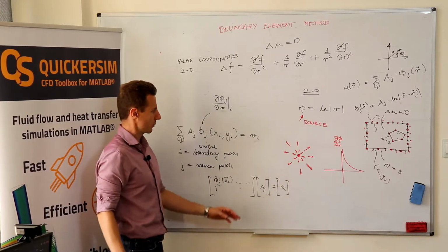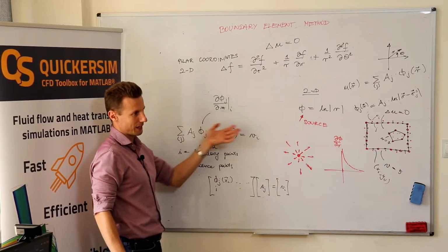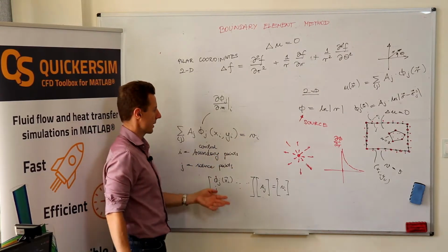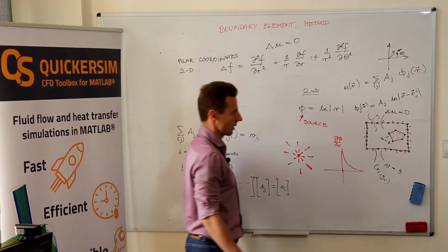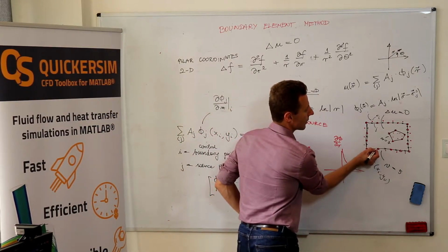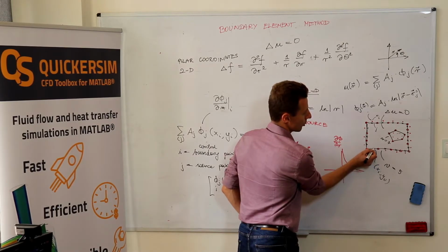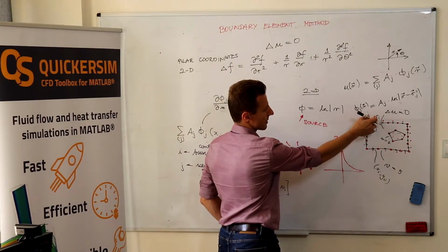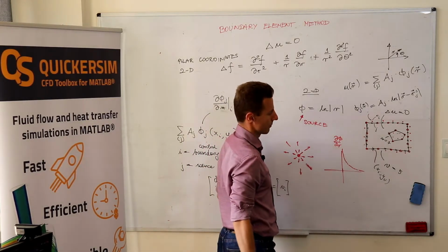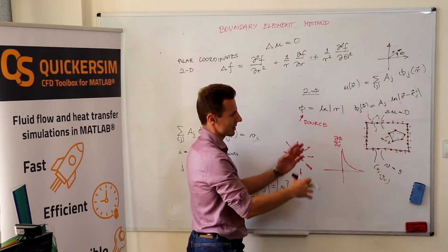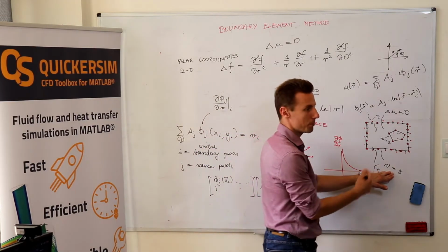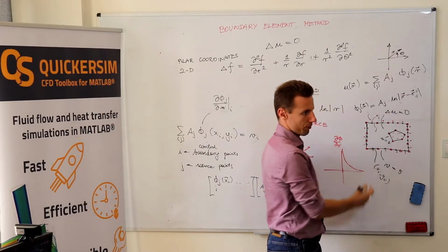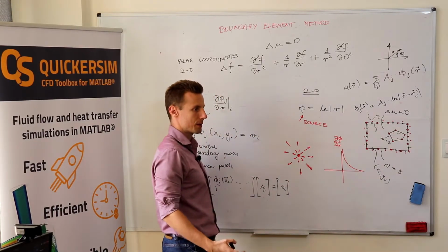Also, good question coming from you. This one is a very, very naive way of implementing the Dirichlet boundary condition. A bit smarter would be to count the contributions this way, that you do not require that the contribution from that source to this control point gives you exactly like the sum of all these values gives you this value, but maybe you would rather want to require that the integral of this element is 5.